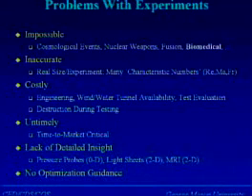They may be inaccurate, and the main reason why experiments are inaccurate is that you have many non-dimensional numbers in an experiment, and you have to match all those non-dimensional numbers in the prototype in order to have that be exactly the same thing that happens in real life. So if we take, for example, I don't know, a missile or a bomb dropping from an airplane, you have the Mach number, you have the Reynolds number, and you have the Froude number. There's three non-dimensional numbers that you have to match there, and it's incredibly difficult to find a wind tunnel anywhere in the world that will match those three numbers.